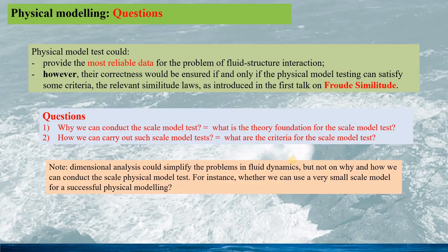But here, we must mention that dimensional analysis is not a guide for the model test, but a method for simplifying the physical modeling. For instance, we might need to vary fewer parameters to get the relation among the variables. This is the same for numerical modeling, in which we often present the results using non-dimensional parameters.